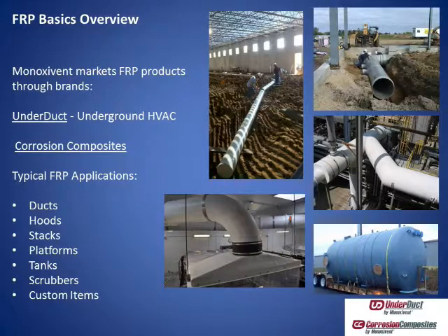The picture on the lower left is a typical wastewater plant. And what you're looking at there is a large hood. I think those hoods were 14 by 8, and they're covering a gravity belt filter press that separates the solids in the solid building.